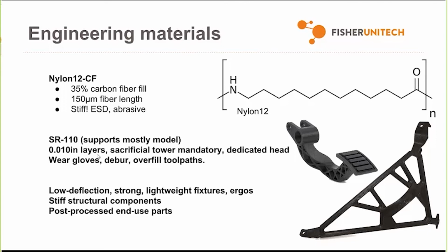So there is a mechanical upgrade involved in order to run it, and that includes a dedicated head. So before you run nylon 12 CF in practice, you need to unload the model material and the support material, power the machine down. You're going to unfasten the head just like a tip change, but then you also unscrew the power cable, disconnect the filament tubes, and remove the head. It doesn't take long, 2-3 minutes. And you put the new carbon fiber head in and reverse that process. Switching the heads around maybe takes 5 minutes, but all told, it takes about a couple hours after you replace the head, to wait for things to heat up and run through some calibration. It's that shutdown process that slows things a bit.